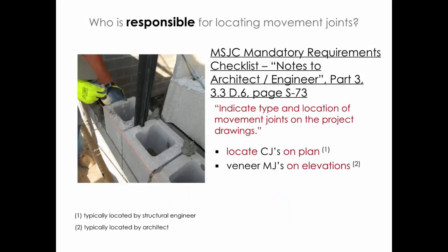Jeff said get me involved early. A lot of times I get involved late in movement joint conversations. That's just not a good time. Contractors shouldn't be figuring out movement joint, control joint locations. It changes all the forces that go through your structural elements within your design. We have to know where they are before we can design anything. So I don't know how we could leave that up to contractors to locate them.